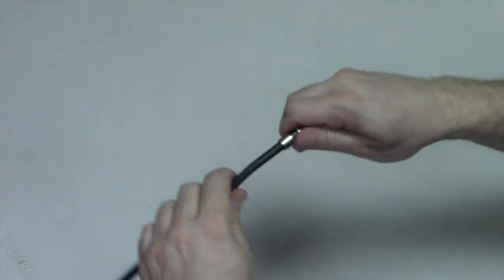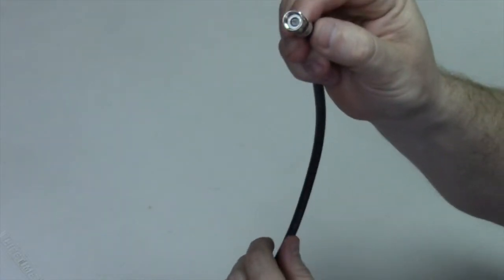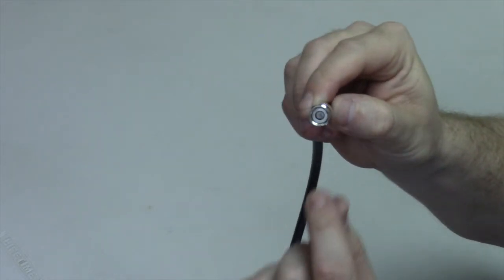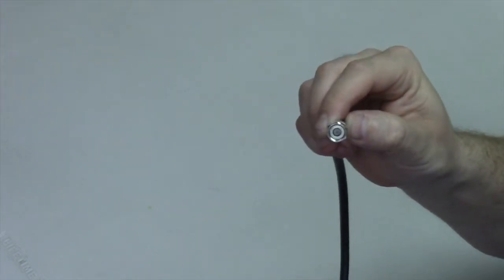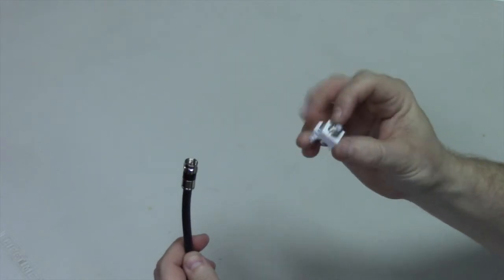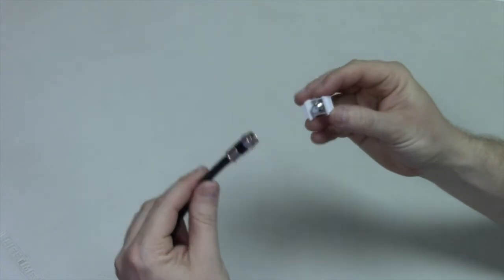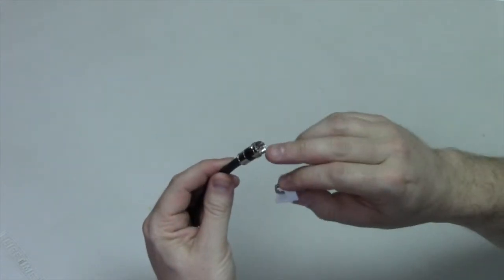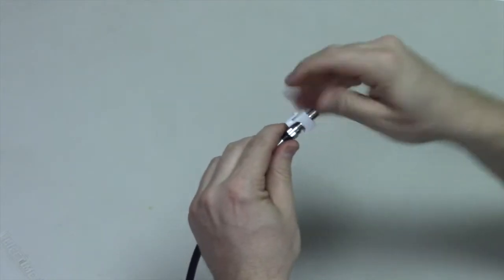Make sure the cable has been crimped on securely. Also make sure that the center conductor is still nice and straight and the dielectric is still centered and flush. Once you've properly crimped on the F connector, you can add a Keystone F connector. The Keystone F connector is the part that will snap into the wall plate. To do this, simply line up the center conductor with the hole in the Keystone F connector and twist on until it is nice and snug.